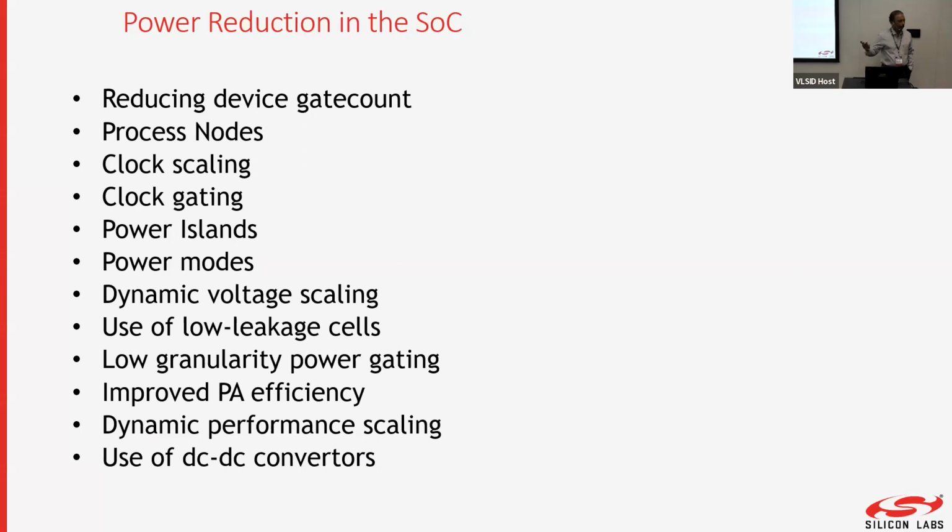Then you have clock gating. Why reduce a clock speed when you can turn it off completely? So can you not gate the clock? If that logic that you have is not being used at the moment, why bother feeding a clock to it? When data itself is not changing, why are you feeding clock? Then you gate the clock. And there are a lot of techniques for doing it.